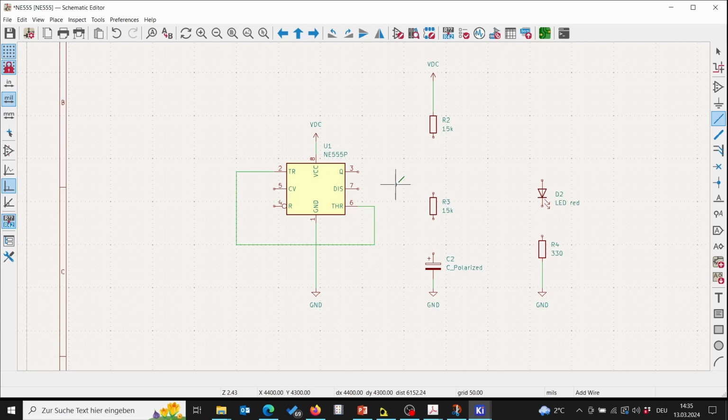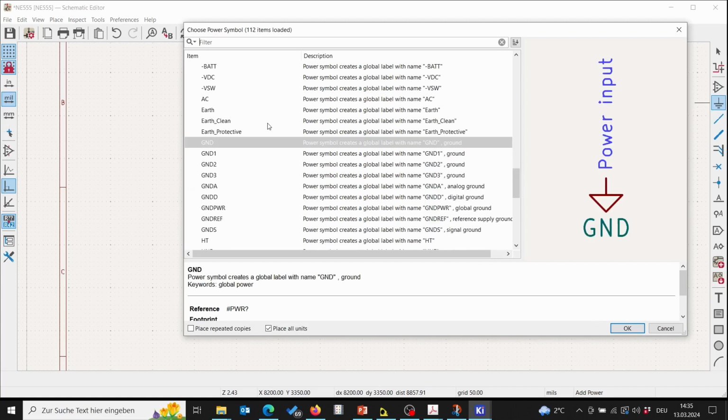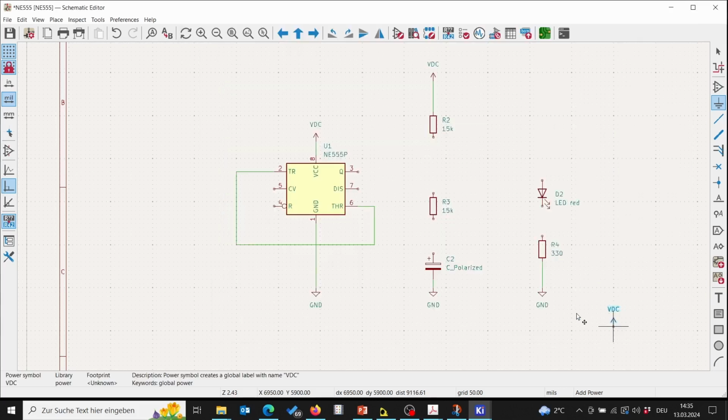And then we see that we have to connect the reset to VCC. Again, we take here our VCC symbol and we don't draw a line. We took VDC, right? So we take VDC, re-rotate it, place it, W, hover over it, W, connected, left click, connected, and finished.